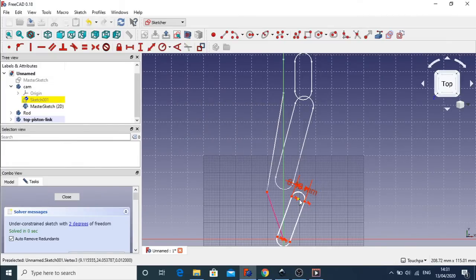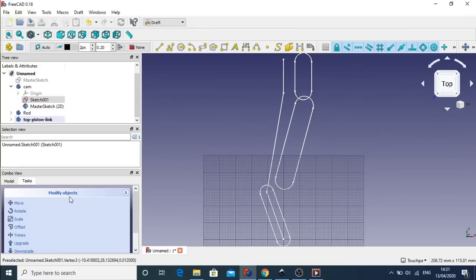That'll do, and I'm just going to leave the height constraint as it is for the time being, and I'm going to constrain those 2 points there. So now you can see that's gone green, so that's a fixed constraint against that length there. So anything we do in the master sketch will actually move that. So I'll show you that now.